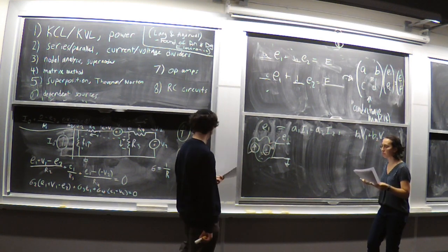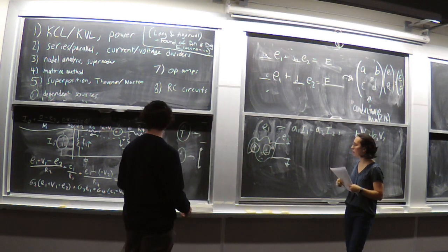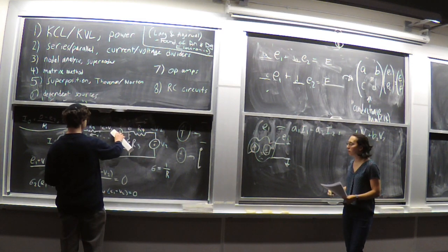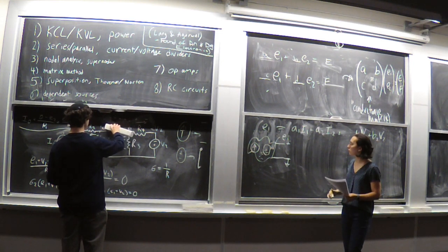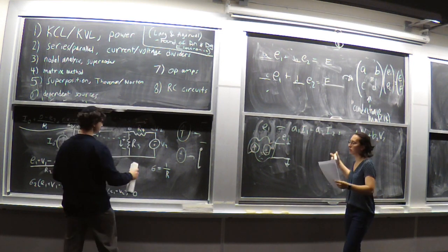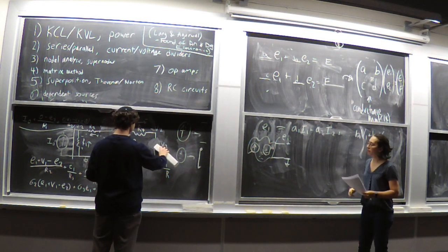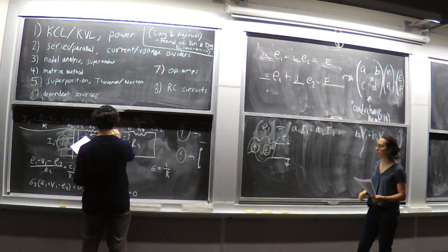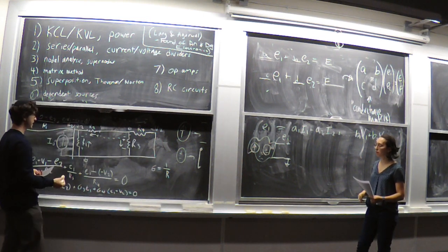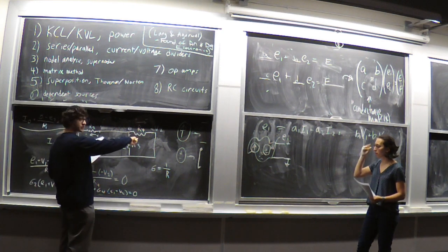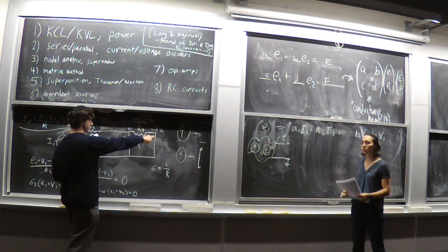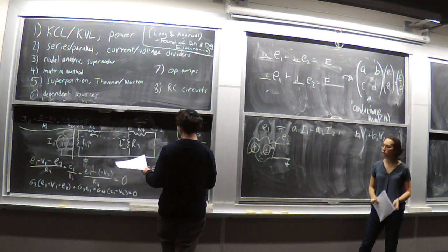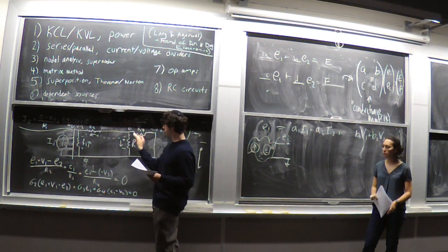Yeah, so, right, so if we turn off V2 and V1 for a moment, we'll remember that these are here. We could redraw. I think it'll work out. So first, we're just left with this current source. And as I was saying before, right now these two resistors are in parallel with each other because they share this terminal and they share that terminal. So we get R3 in parallel with R4. That then is in series with R2, right?